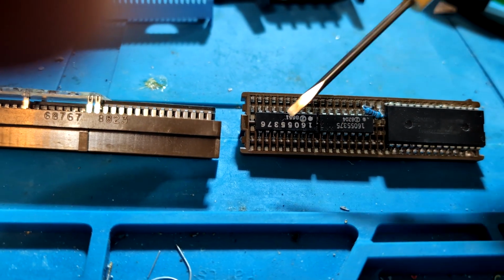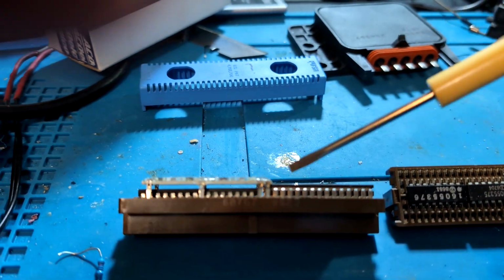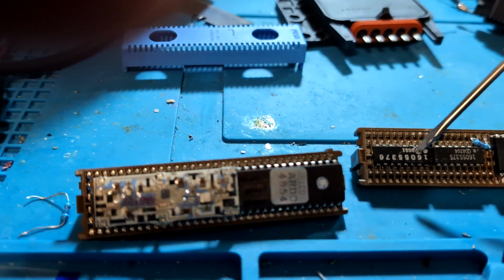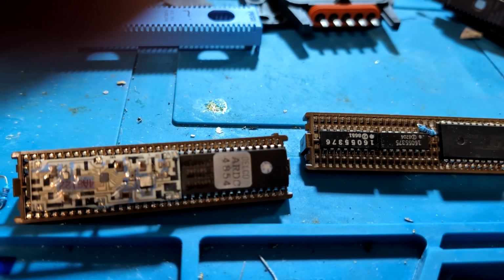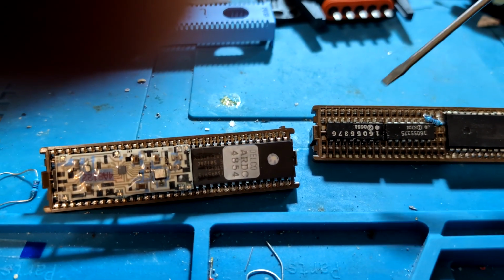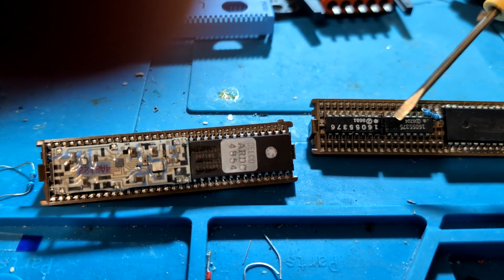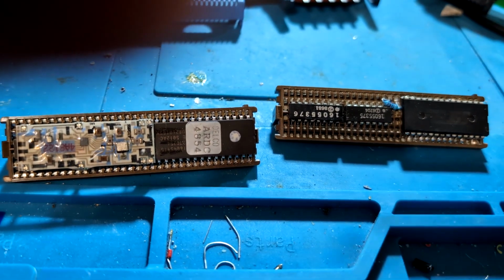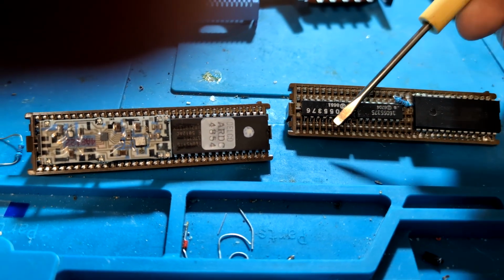So these are V8 chips, spec'd to run a V8. This one is not. That's essentially the difference between these Memcals. In the event of a limp home mode situation where you're relying on these CalPack chips to get you home, this is going to be calibrated to run a V8 engine, your 350 or 305, whatever it may be. So that is the main consideration with these different Memcals.